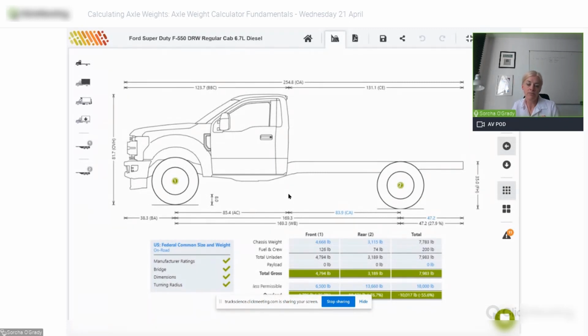Your calculations may all be different, but you'll go through the same process every time to input information and generate results. We're going to use the left-hand side of the screen to input your vehicle, body, equipment, and payload information. The bottom part we'll use to verify compliance with manufacturer and regulation limits and to determine maximum achievable payload. In the right-hand side, we switch views and examine outputs. And at the top, we can print, save, and share our calculation, as well as define our preferences.